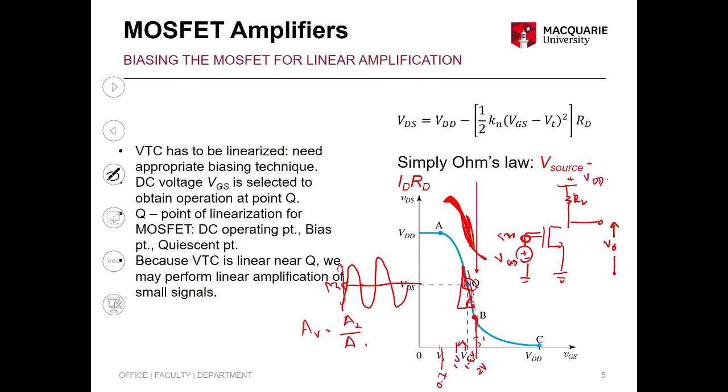Similarly, in your lab 2, when you tuned the circuit, some of you couldn't get the gain above 25 dB, right? One thing you could have done is increase the bias voltage without tuning, and it just gives a bump.